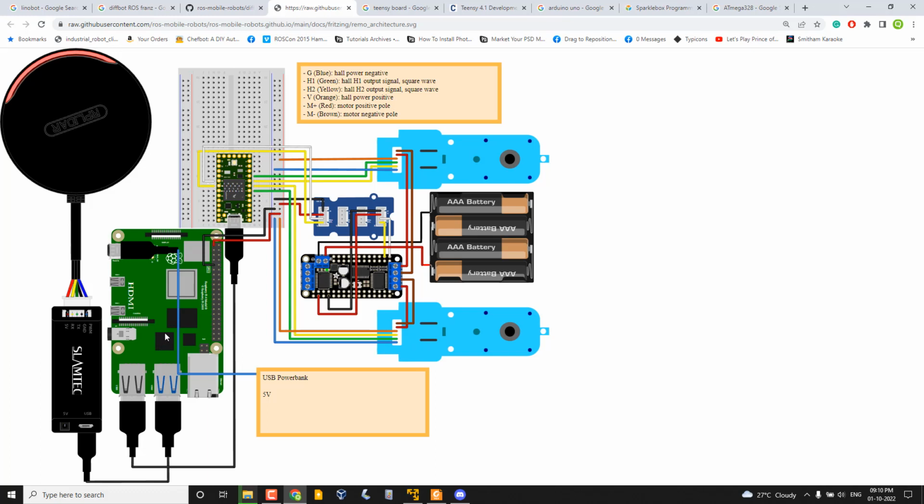I'm not sure if you have worked with this board, but literally it's like a plug and play thing. If you plug in this board, it will be detected as devices like /dev/ttyUSB0, USB1, something like that. Okay, so after getting the device, you can communicate through pyserial or some kind of, I think we have discussed this in the intro class, like we can communicate using the serial protocol.